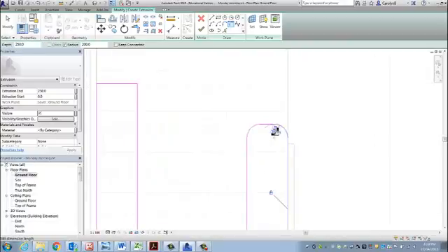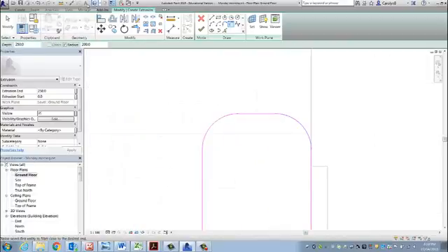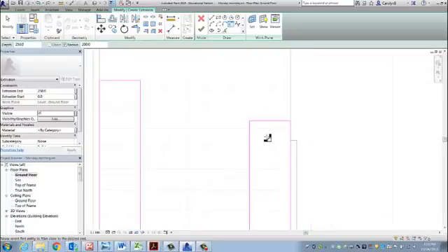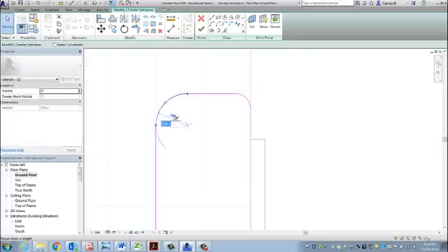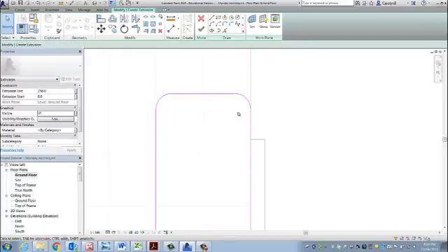Clicking again on the two sides that I want to retain. So I'll just do that again. As I zoom in this time, I'm still in the extrusion, I'm still drawing my 2D profile. Fillet arc, I click radius, I nominate 200, and I'm clicking on the lines that I want to keep. Notice I can adjust that if I want to. I can click on that, and the lines around it will automatically update as well.